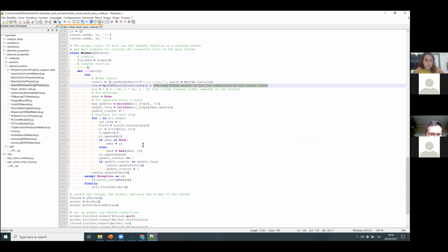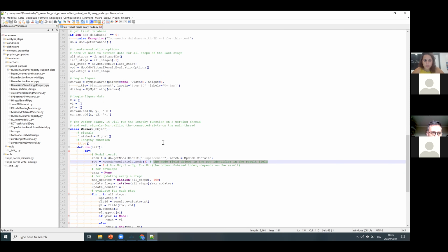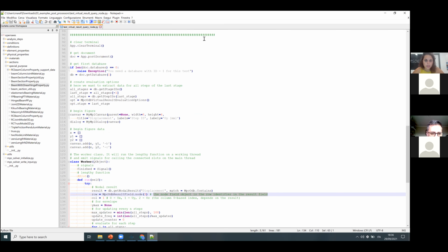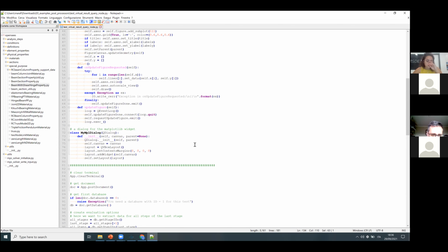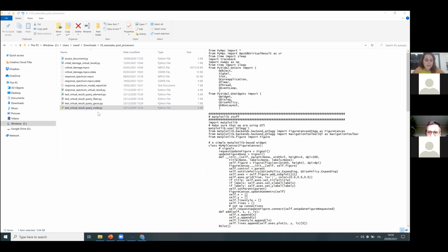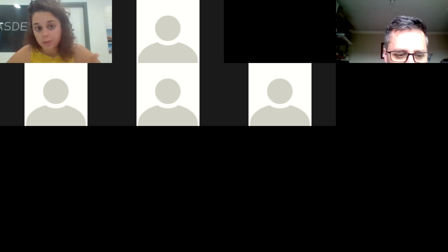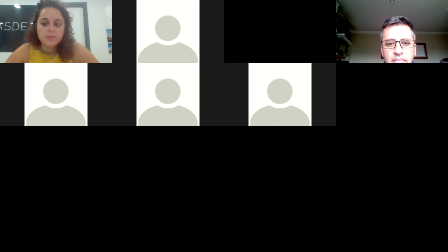Okay, this is a whole script to create even a plot, and I don't know if you have heard about using call types and the worker and the process thread. Anyway, this is a bit more complicated to use. I would not suggest it, now that I'm thinking about it. But if you want to write together a script on how to access a specific node and save the value in a specific text file from the Python API, then I would suggest maybe that the fastest way is to use the STKO recorder inside of a custom command in your analysis steps.